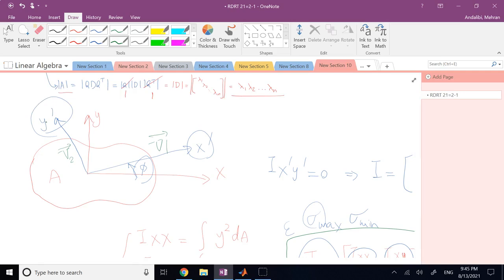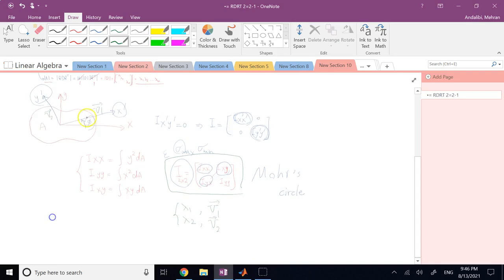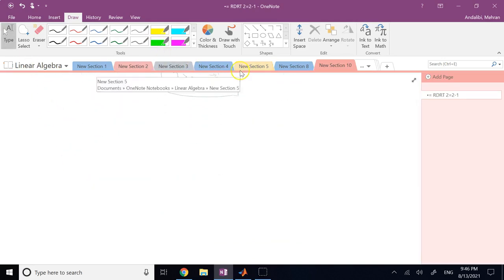Right? Just like that. So if you did it by the Mohr circle or by the analytic formula, where it was calculated based on angle, and then you took the derivative with respect to angle and set it equal to 0 to give you the angle of the principal axis, another way to do it is simply by doing an eigenvalue problem.